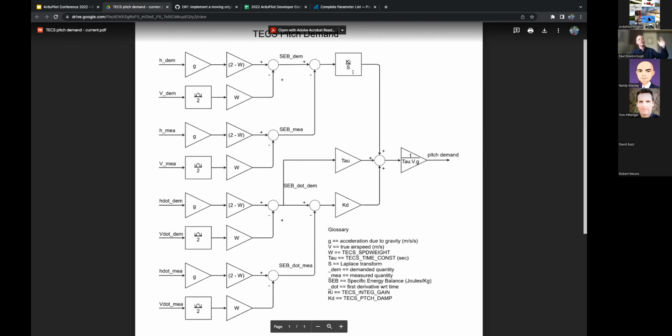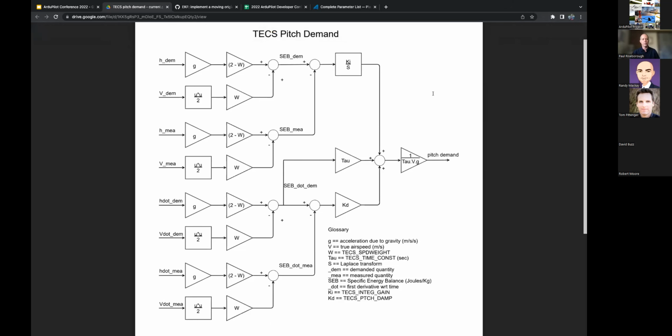And then the integrator has to wind off, and you end up overshooting your height and then coming back down again until you level off. And this also happens the other way. If you can't meet your descent profile and you follow the descent down and level off, you can end up with this dip where it undershoots the descent. And that's a bit more alarming, particularly if you're leveling a descent off at 35 meters and the treetops are at 25.